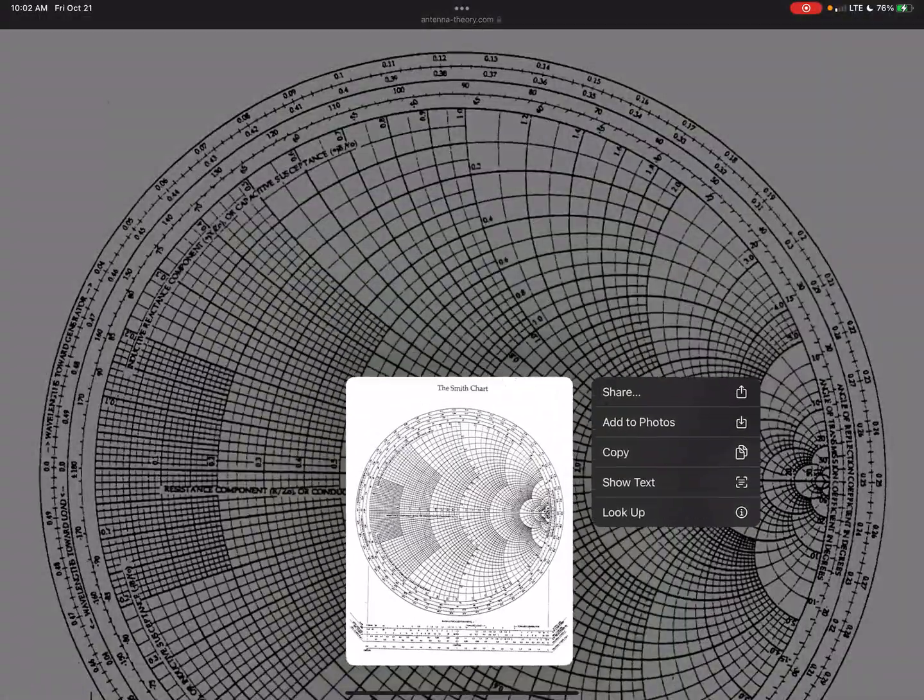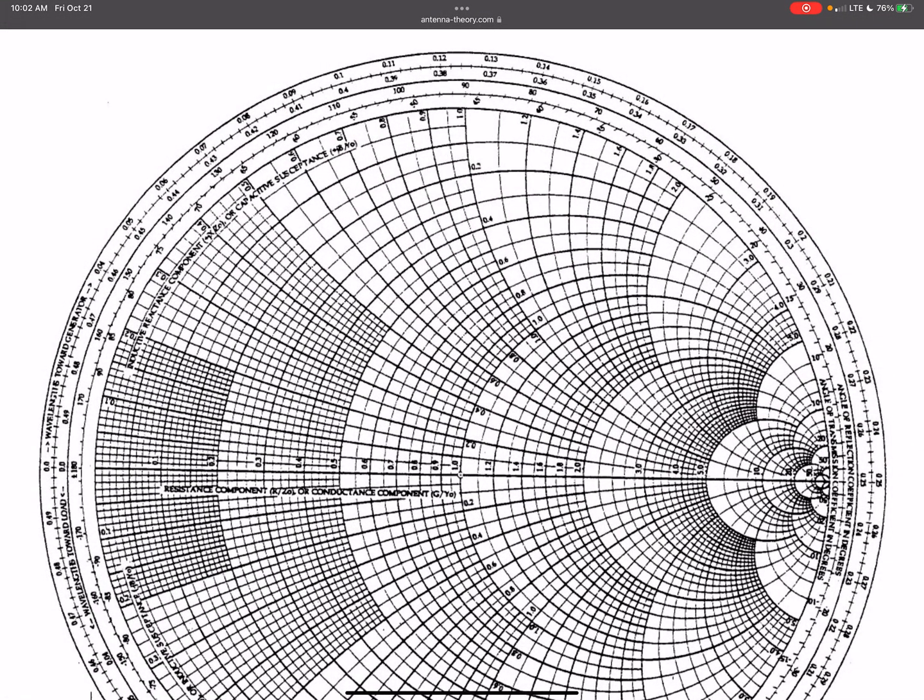So let's say I draw my A here. Okay, so OA, I can say, well, physically, this is like an 8.5 by 11 sheet. Say that's 2 centimeters on my chart. And then M is over here. Let's say on my chart, OM is like 4 centimeters. So the amplitude of OA, I can physically measure it, and gamma sub L is OA over OM.